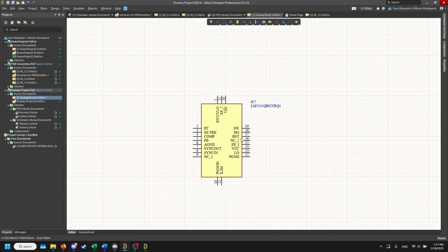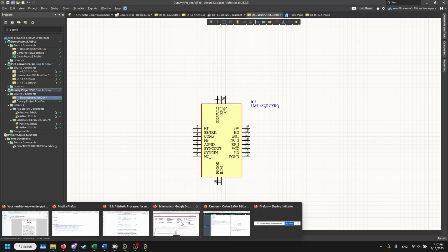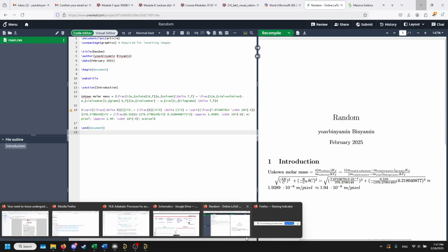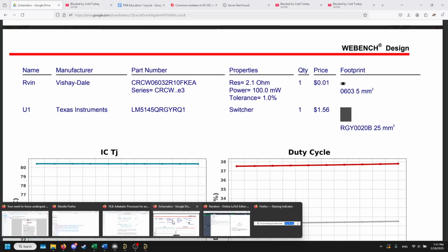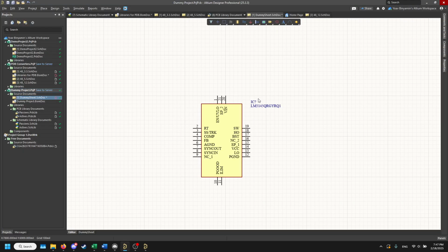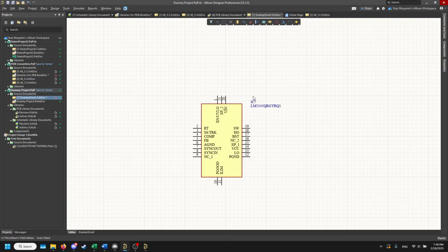However, we have a few differences from the schematic that we really want. So the first thing you're gonna, what was this? It's like, man, I should get a bunch of stuff cleared out. First of all, the designator isn't right. So you'll notice here it's IC question mark. First of all, it's question mark, and second of all, for IC you want U typically, not IC.